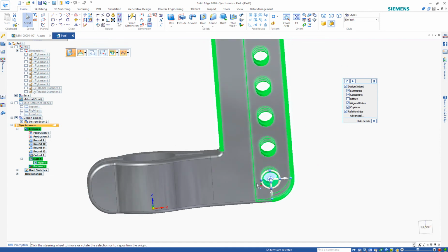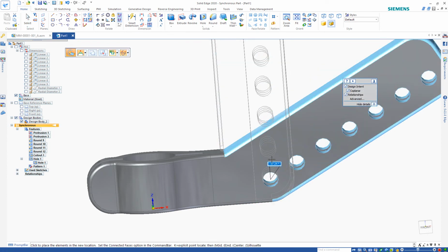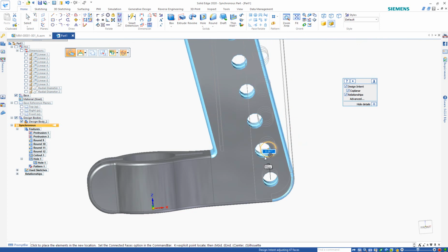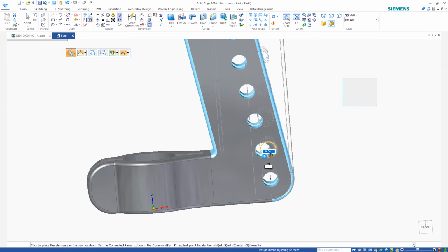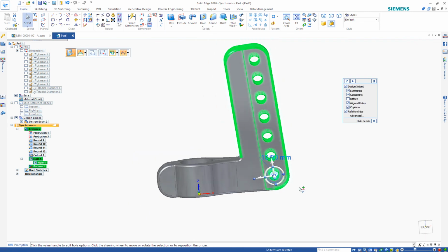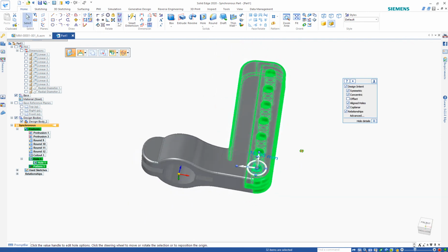now you will see this wheel pops up. It should be automatically attached to the center of the hole if you select it right. If you see this wheel to be somewhere else, just click on the center of it like this and move and attach it to the center of this round. Okay? Then now we just click on the wheel here and you type in 5 and enter. It will just give you a 5-degree tilt easily like this.